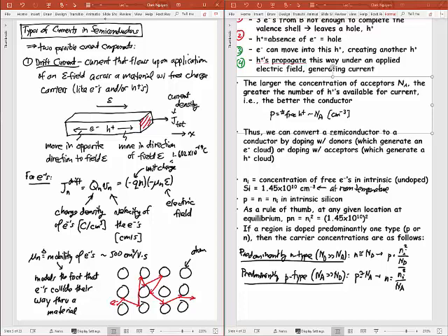And so because of that, I'm multiplying my electric field by some mobility. That mobility is modeling how this electron is moving by colliding through. It's slowing down the whole thing because the electron is not going as fast as you might expect it to. So this kind of motion, where an electron is colliding its way from left to right when our electric field is like this, is what we call drift. So when I say drift current, I mean this.